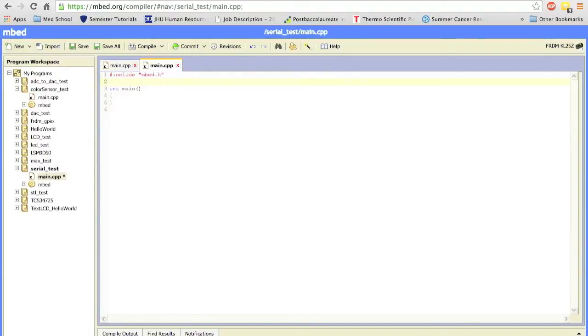All right, so in this tutorial, what we're going to be covering is serial communications. It's also called UART, which stands for Universal Asynchronous Receiver Transmitter. What this pretty much does is it allows you, with two wires, to connect to any sort of other digital device. And the advantage of this, in the case of the computer, is that you can actually transmit via this serial communication link from your microcontroller to your computer any sort of random data.